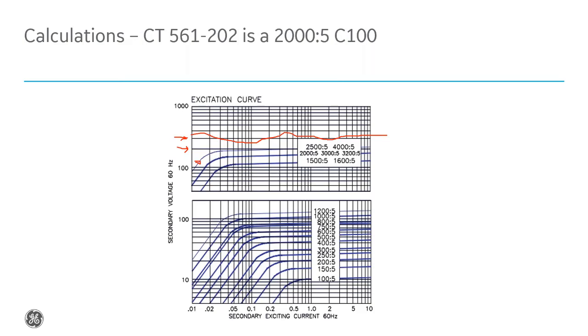we multiply that times the 2,000, that's right at 100 volts. If we end up with a setting that's more realistic of 75 milliamps, so that'd be 0.075 times that 2,000 ohm resistor, that's about 150 volts.